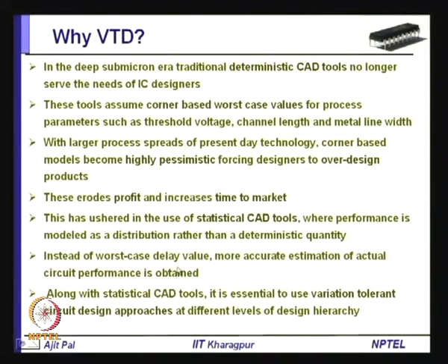So, instead of worst case delay value, a more accurate estimation of actual circuit performance is obtained whenever you use these statistical techniques. And along with statistical CAD tools, it is essential to use variation tolerant circuit design approaches at different levels of design hierarchy. I shall discuss some of the variation tolerant circuit design approaches which can be used at different levels of design hierarchy.